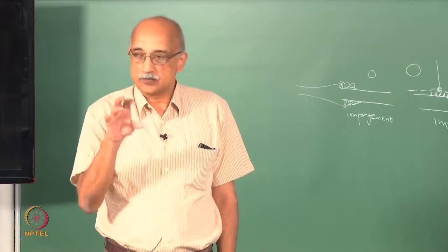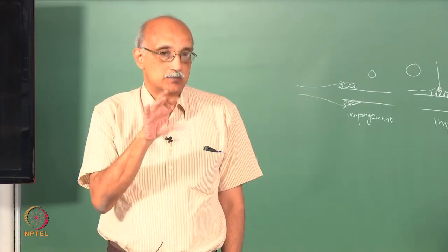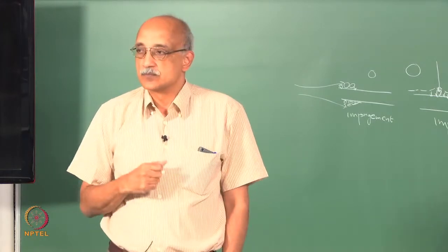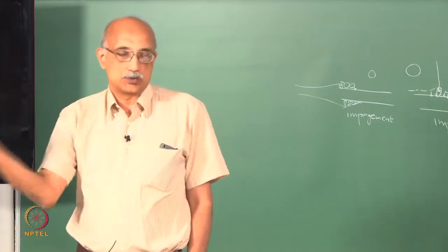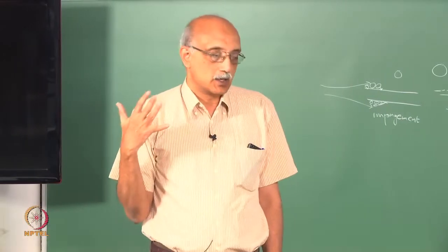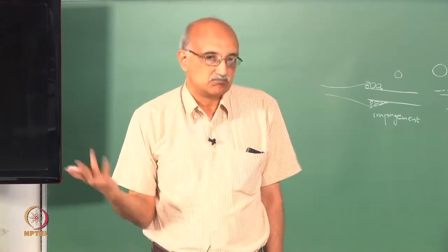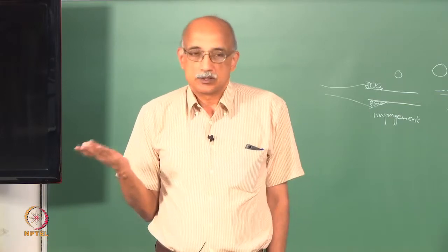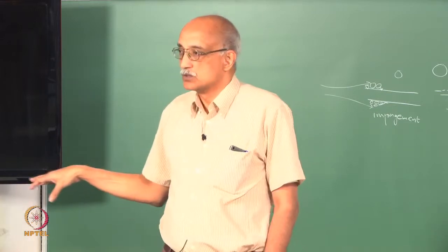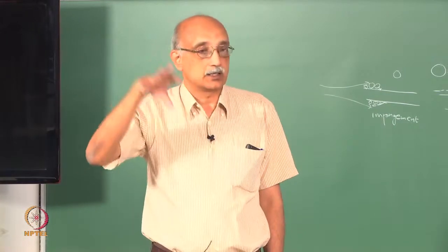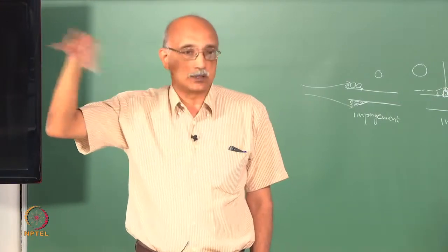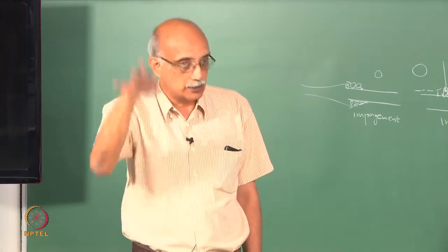the whole facility in such a way that the particle count per unit volume of air inside the room meets a certain specification. So, when you think about it, suppose you want this room to meet a specification of, let us say, no more than 100 particles larger than half a micron per cubic foot. How would you do it? The first thing you need to do is control airflow in and airflow out. You have to make sure that any air that comes into this room is directed through filters which will remove particles and other contaminants from the air and allow the air then to enter the room.